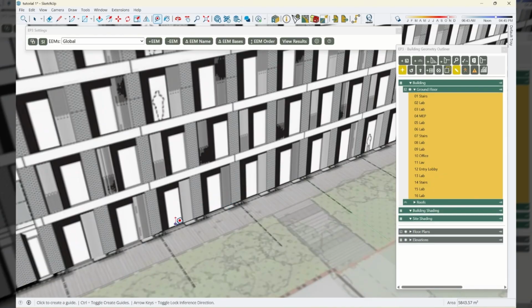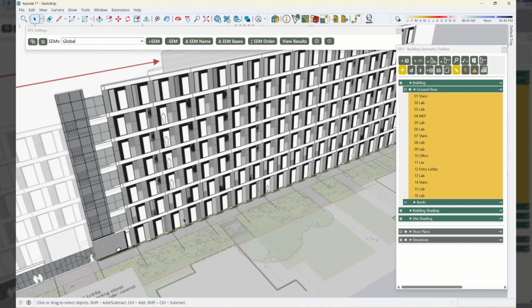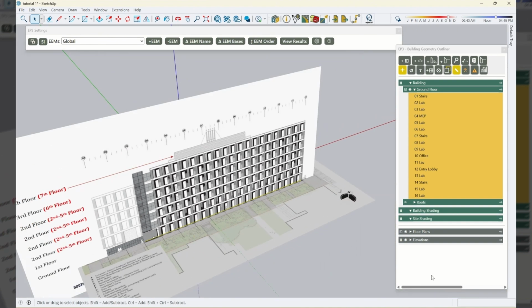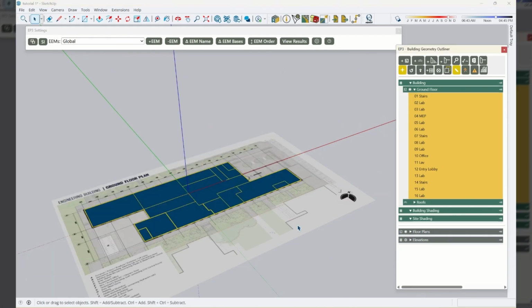So I'm going to zoom in, and I can choose a spot on the ground, and then I can just measure up. And if you look in the lower right, you'll see that I'm getting something that's real close to 4 meters. So I know that my next floor height is going to be 4 meters up from this ground floor. So I'll hide my elevation.